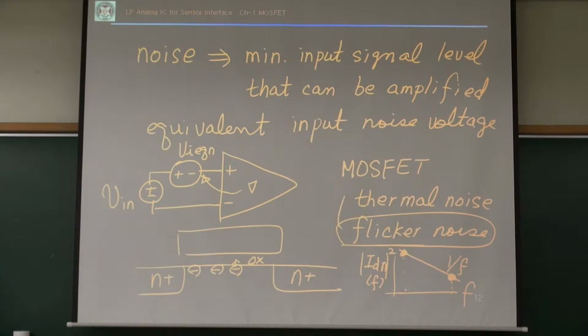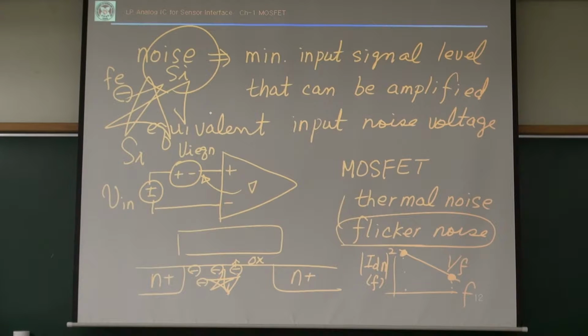And then thermal noise is just random Brownian motion. Electrons passing by just move around. This is my free electron, there are silicon atoms here and there, and it goes in a random motion. Even though there is an electric field, the net movement follows the electric field, but it undergoes a very irregular thermal motion. Because of that, we have thermal noise.